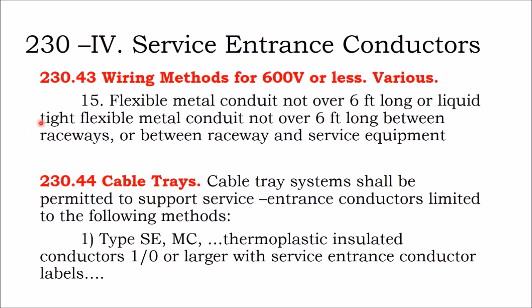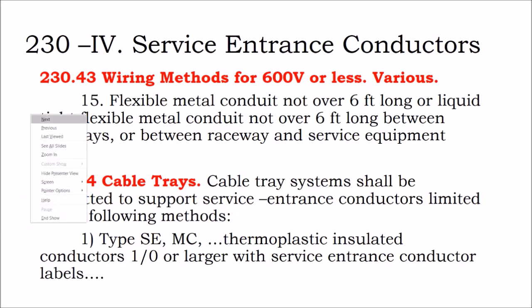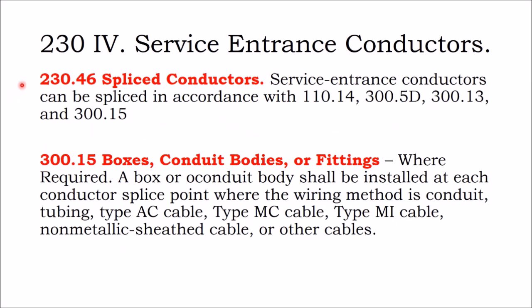There's certain restrictions. Flexible metal conduit for service entrances can't be over 6 feet long between raceways and other service equipment. Cable trays can be used to support service entrance conductors, but only certain types. Different locations on where you can splice conductors.